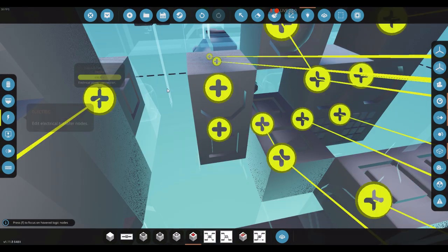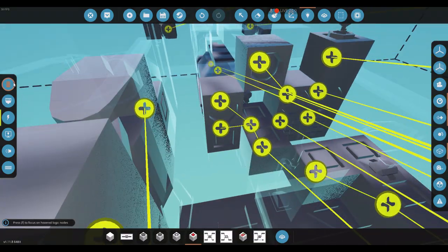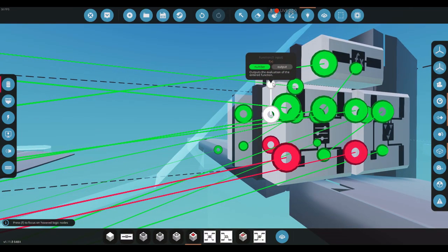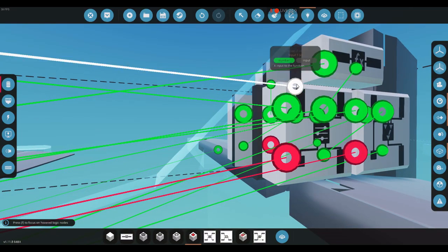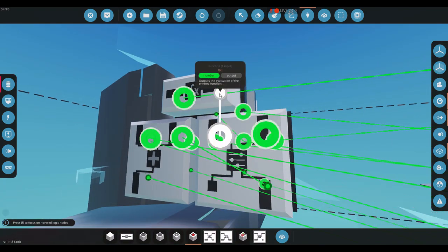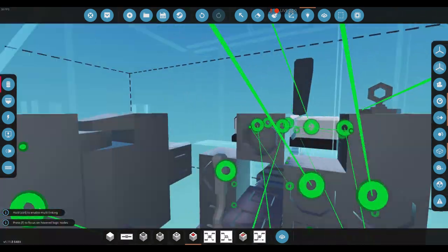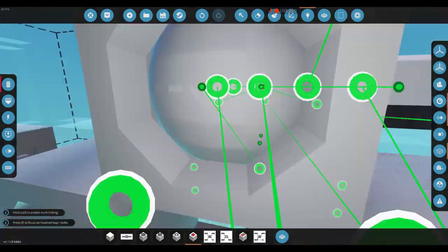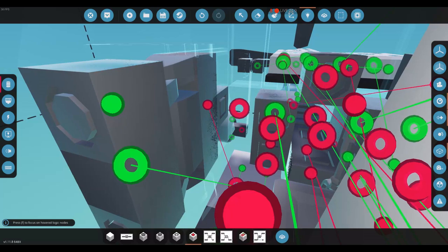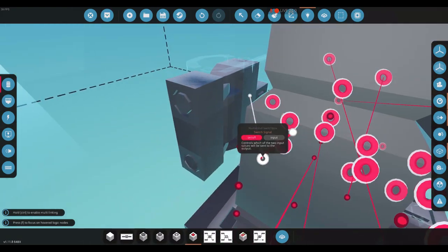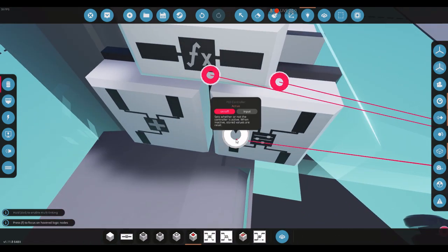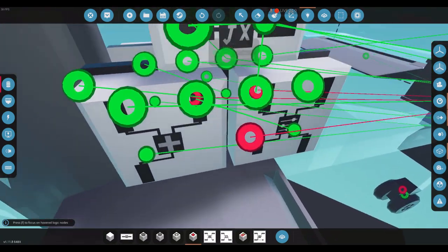We're going to hook these up to electricity. And now what we're going to do is, for one, what we plugged into our PID process variable, directly from the function block that's inputting our compass heading, we are also going to put that over to our dial. We're going to put this into our compass bearing dial so we can see what our compass bearing is. It's going to tell us a value between 0 and +360. We're going to take the toggle button we placed moments ago to the PID active. So when we want to turn on the system, we hit that.